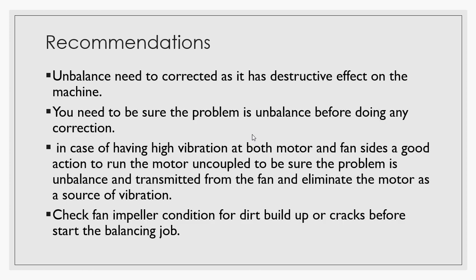And also if the fan and the motor are belt driven, the same condition applies, you can remove the belt. Be careful when you measure 1x on the motor and fan and it's belt driven: you will find two 1x, 1x for the motor and 1x for the fan, because the speed is different. And when you do balancing, be sure that you put your reflective tape on the fan shaft, not the motor shaft. Check the fan impeller condition for dirt buildup or cracks before you start the balancing job.